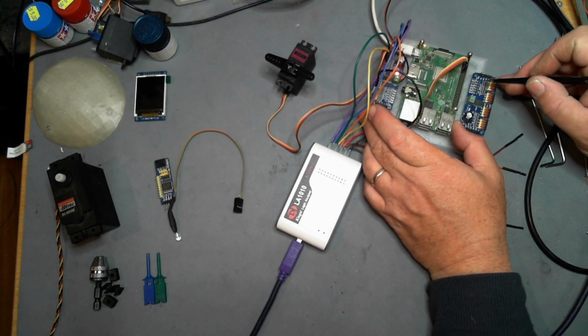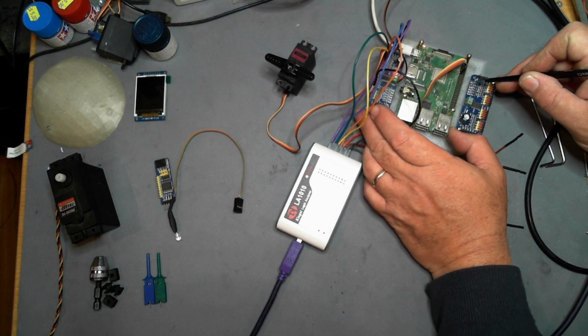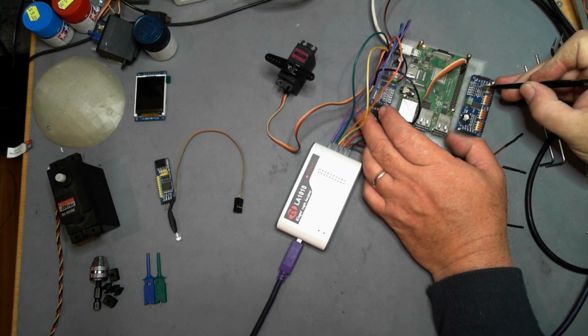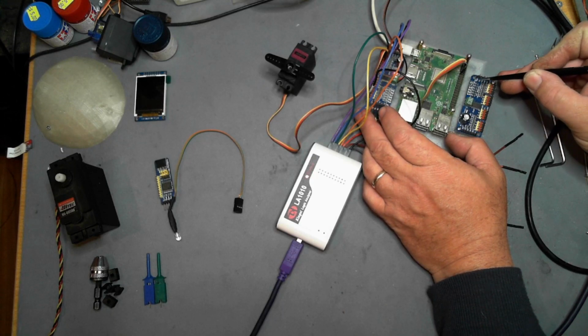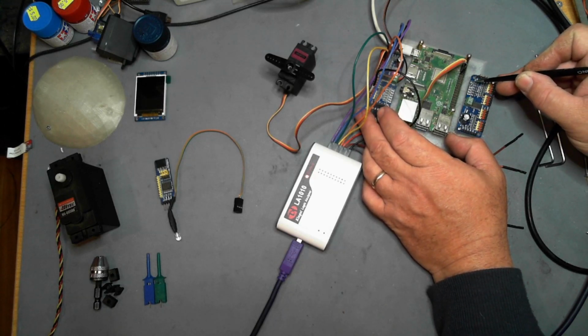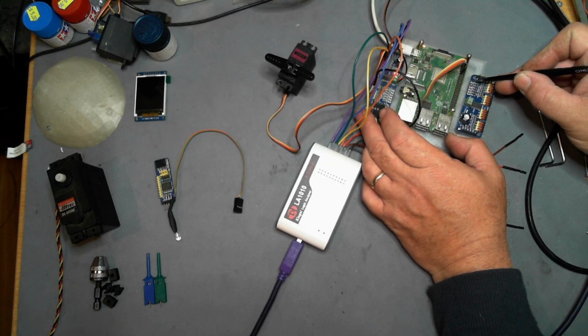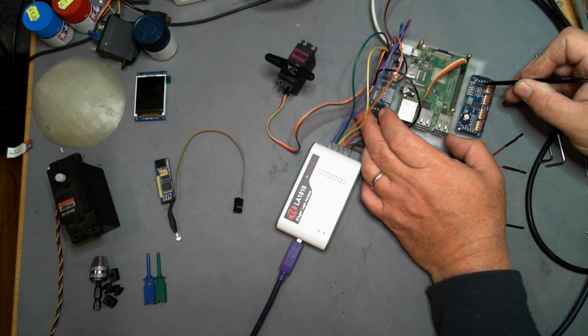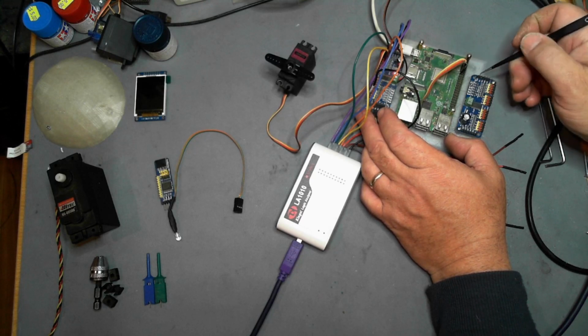So over here are a heap of solder pads, and if you short these solder pads across, it will change the address of the device. So you've got A0, A1, A2, A3, A4 and A5. If you short this pad here, the A0, add 1 to the address. If you short this pad, add 2. So in this particular board, this one is shorted, so this one would be an address 42 hex.